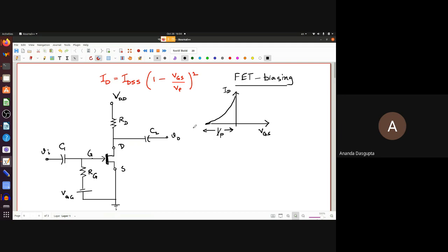So if you put a big enough reverse bias on the gate source, between the gate and the source, the depletion region there, if you remember, this is what the JFET looks like. You have a channel which is N-type, and you have basically put a P-type region around that, and this is what the gate is.